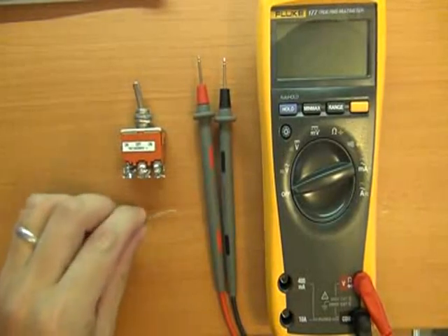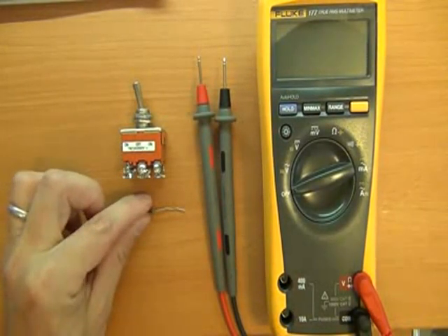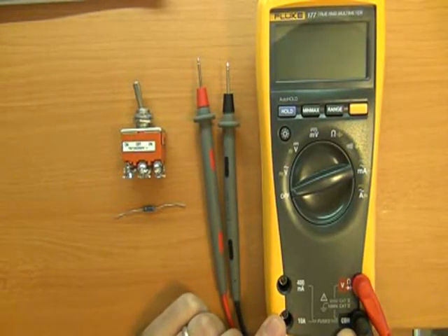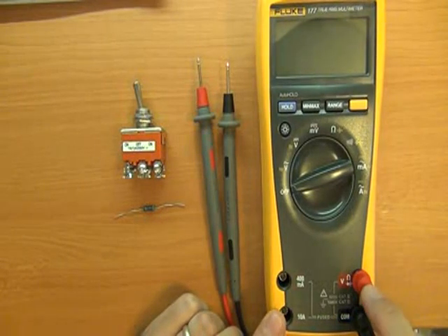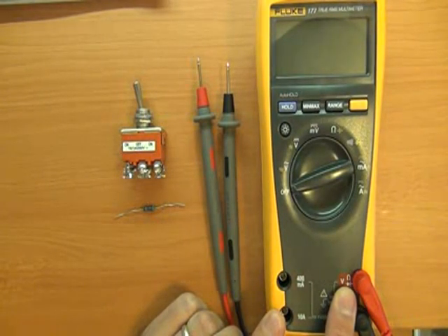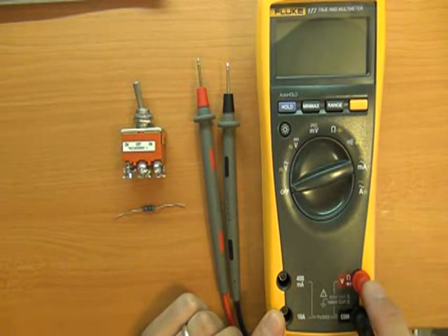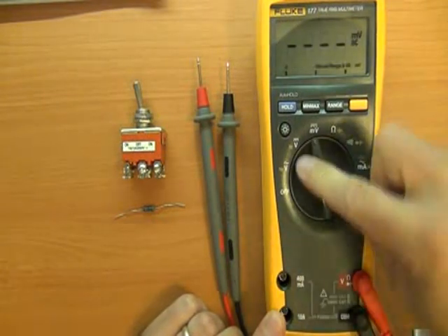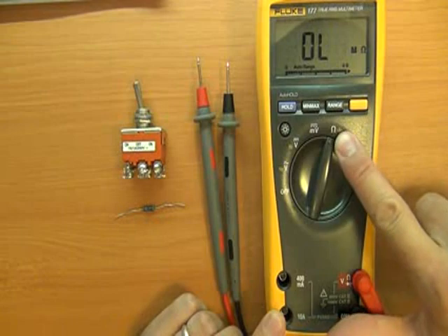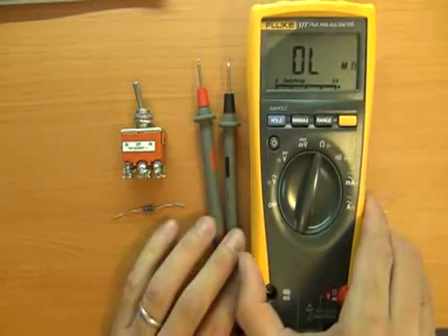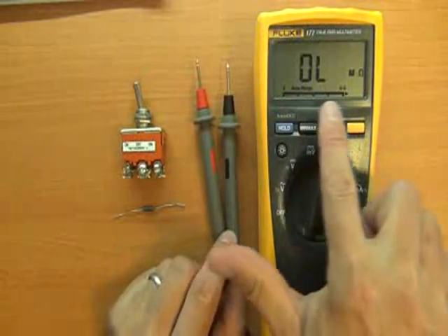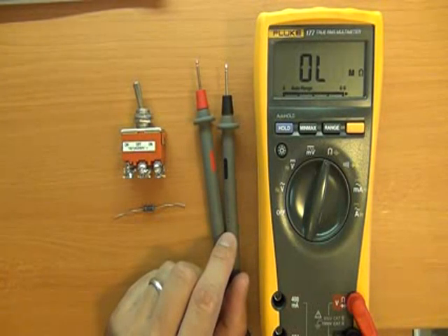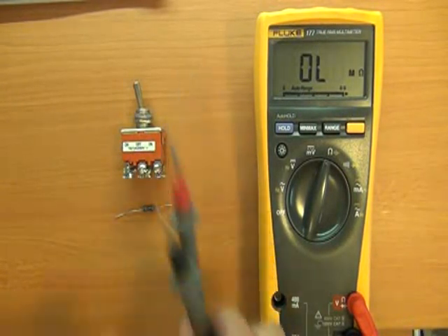Okay, so let's get down to how we actually measure resistance with a multimeter. So again, as we had before, our black one is in the common connector on the multimeter. Our red one is on that omega sign, or ohms, on the multimeter, which is normally shared with your voltage measurement. And then we just flick our selector through to the ohm, or that omega sign again. And the multimeter is set up to auto range, and by default you'll see it sits here in this overload mode, because basically it's got nothing to measure.